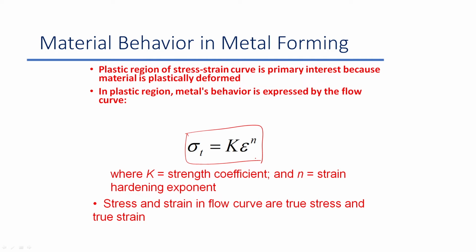Although the relationship is well known, the description of these kinds of relationships depends on the values of K and n. And I showed you in previous lectures that n is always less than 1. That is why nonlinearity comes into the picture. When you see the stress strain curves, they are nonlinear in terms of stress strain. So, initially you have an elastic portion, then it starts to become very nonlinear, right. And this nonlinearity is basically because of the value of n.